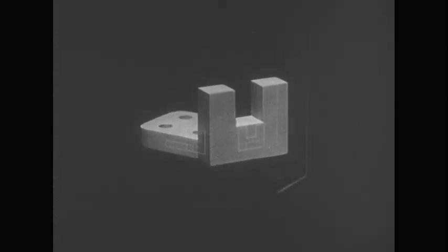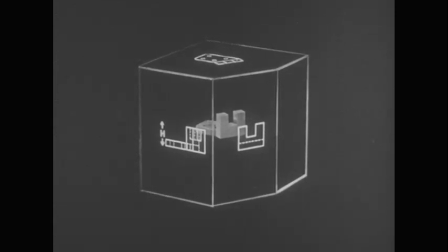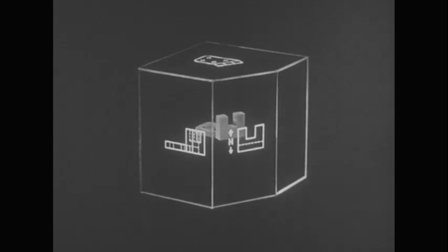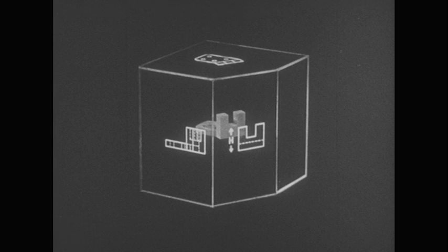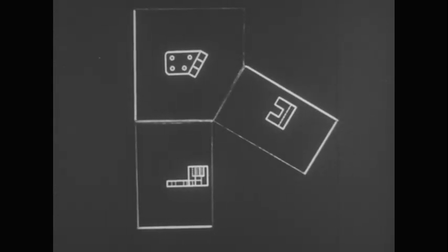If you study this object and its planes of projection, you will see that the dimensions of the auxiliary view can be secured from the principal views. The view which shows the slanting face foreshortened, here the front view, has one dimension, the height, which also appears on the auxiliary view. So in constructing this auxiliary view, you get the height from the front view. On the view which shows the slanting face as an edge, here the top view, the other dimension of the auxiliary view appears. Therefore, you can secure the second dimension for the auxiliary from the top view.